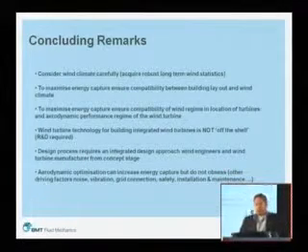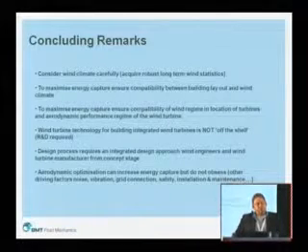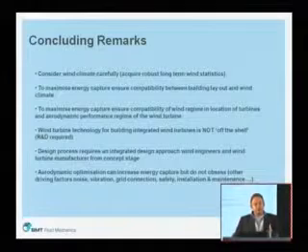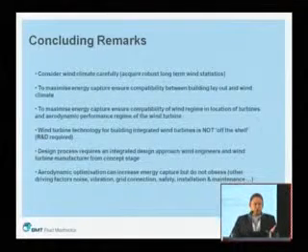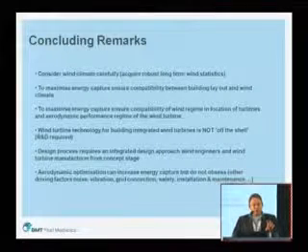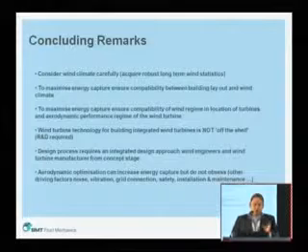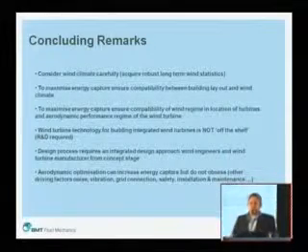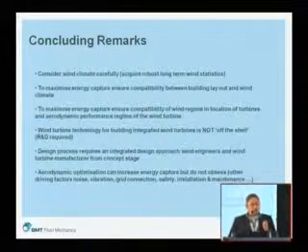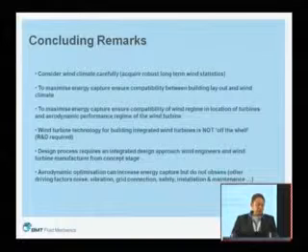The third point is quite an important one as well. You need to accept that it's an integrated design process between understanding the wind regime that is available on the building and choosing and specifying the wind turbine technology. That's quite a key thing, because most of the wind turbines that are commercially available are not off the shelf.